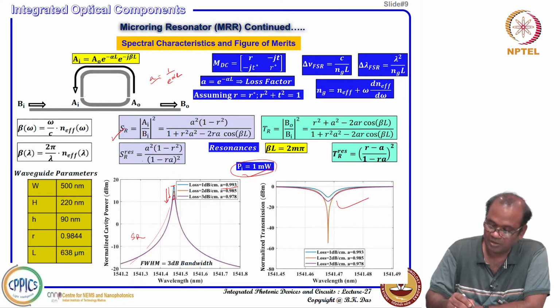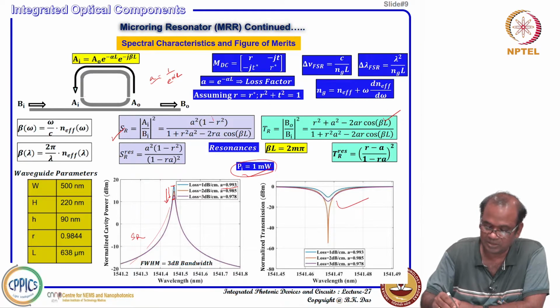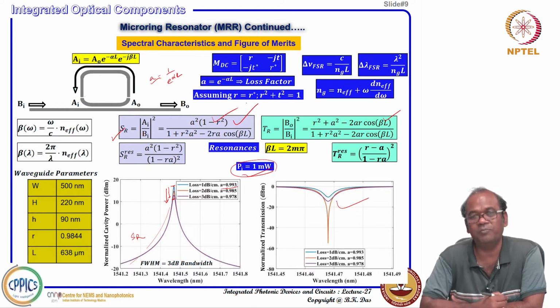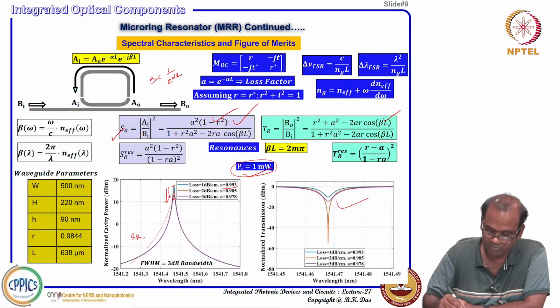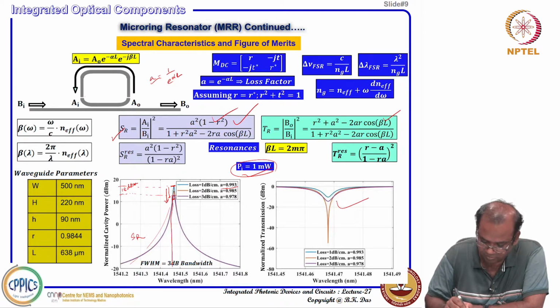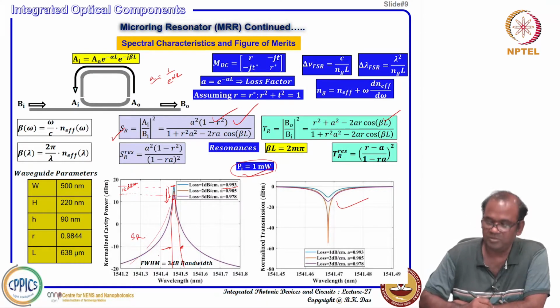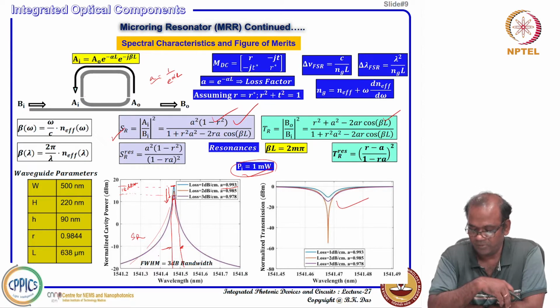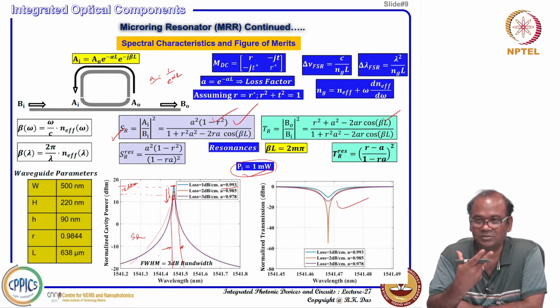We can numerically simulate this curve, and this curve specifically is very important. If I plot this one, I will get this, and I see that the maximum is happening at about 18 dBm. So, I come down 3 dB to about 15 dBm, and then I see this omega 1 and this lambda 1, and if I estimate this, that will be your 3 dB bandwidth. But can we calculate that analytically?